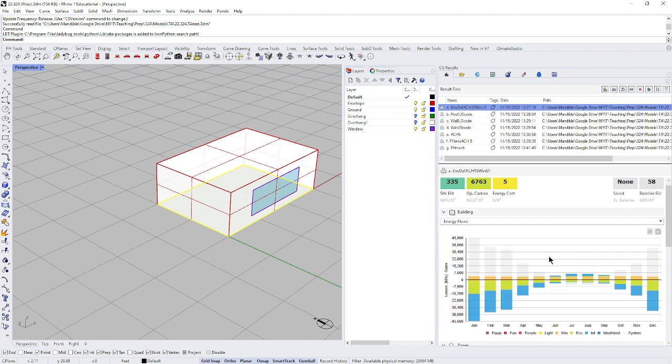energy flows. So what was my envelope? So here's my little code here. Envelope default. So that was concrete for the roof and the walls and the ground. Air changes per hour is 10, which I said would not be typical for that default envelope. And then my window has a U value of 1. So that's what my little code there is. And you can see we got this pretty bad envelope at this point.